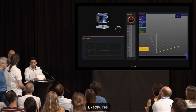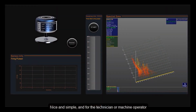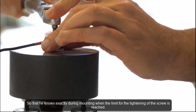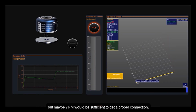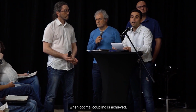Exactly. Nice and simple. And for the technician or machine operator who may have to mount or change a sensor, so that he knows exactly during mounting when the limit for the tightening of the screw is reached. You use the torque wrench to tighten the screw, and usually you apply 8 Nm, but maybe 7 Nm would be sufficient to get a proper connection. Through this visualization, the technician or machine operator sees when the optimal coupling is achieved.